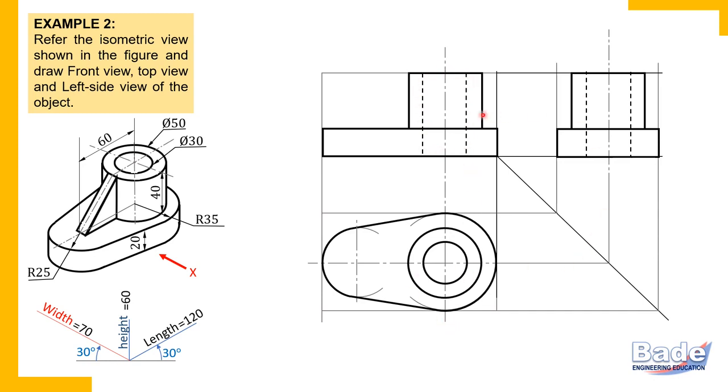Okay. Similarly, draw end projectors from top view to side view and from front view to side view. These end projectors are already there. The entire height of the hole is to be transferred, and that is 40 plus 20, 60. So these two projectors are end projectors, and this is our hole from top to bottom. Okay, so the hole is over. Now the triangular plate. Again, in a view shape, when you say it is a triangular plate, its largest surface is a triangle. That triangular shape will appear in the front view. So in the front view, we'll construct this triangular shape.